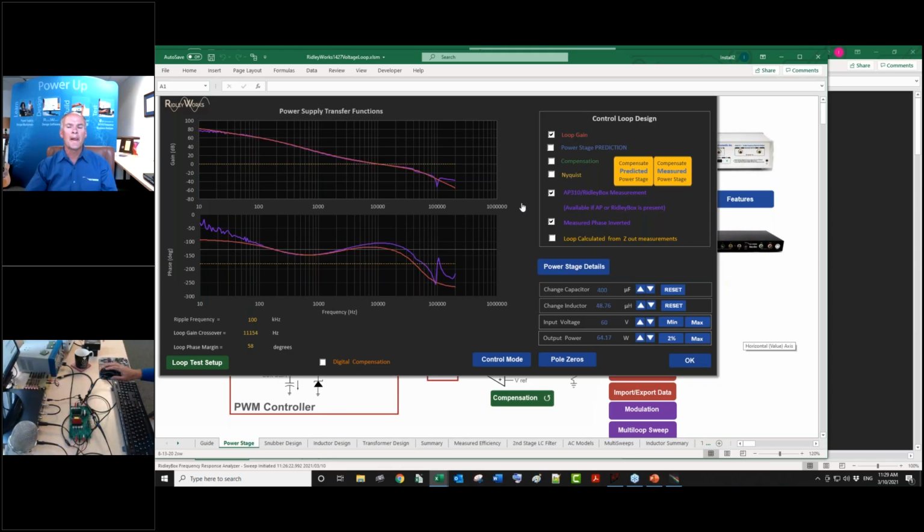Fraser wants to know if we can use this system for inverters. Inverters are tough because you can only measure a steady state system. So if you've got an AC voltage output and you're trying to measure the loop gain of that all along the way, then it's just a totally different measurement. So I would recommend that you look at the work by Kai No, who did topics in inverters, rectifiers, and cycloconverters. And he created a rotating frame of reference for inverters and things.